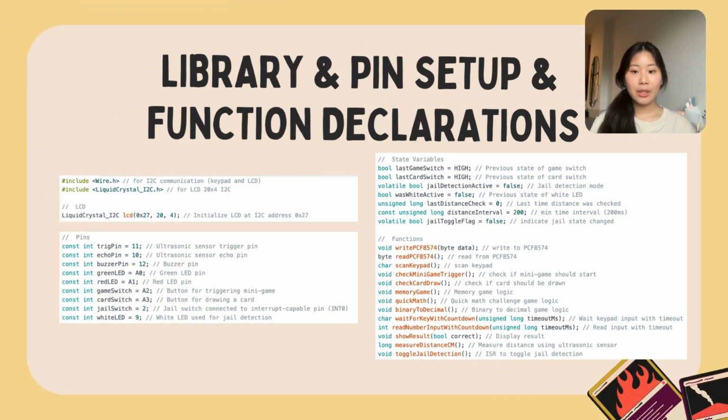This section sets up the core components for Micropoly. We include libraries for I2C communication and the 20x4 LCD display. Then we define the LCD and the keypad, which use a PCF8574 I2C expander. Next, we assign pin numbers for ultrasonic sensor, buzzer, LEDs, and switches. Include a jail switch connected to interrupt pin. Finally, we declare key state variables to manage button press, jail mode, and timing, and list all function prototypes used throughout the program.